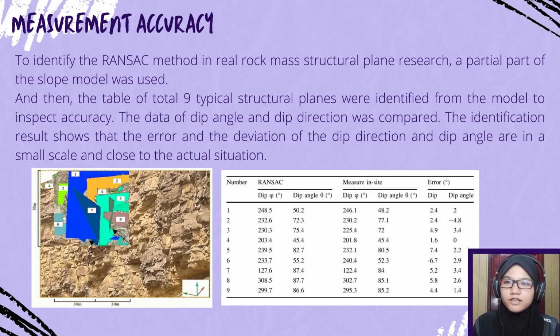As the figure down below, the right side shows the table of comparison of structural planes measured inside and generated by the RANSAC method, while the left side shows the figure of characteristic structural plane identification of the 3D terrace model built with point clouds by the RANSAC method.